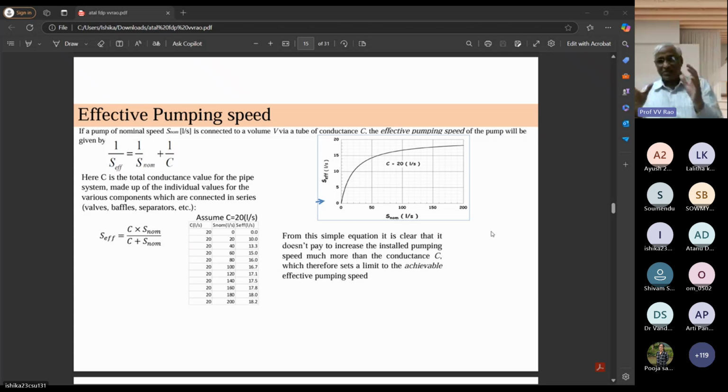So this is the system design, one of the most important aspects. System design from the semiconductor point of view, what material, what temperature, that's another game. That's a material science game. That's not vacuum system design. Vacuum system design means what? It should not leak, it should not degas, and it should be able to be pumped very fast.